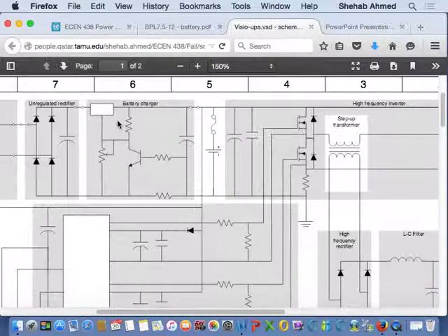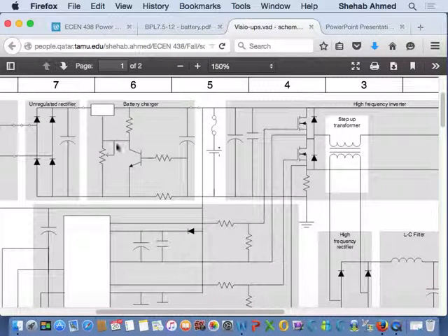So everybody gets that? So we know that this is bad design. This is very bad design, but we added it in there intentionally, right? To make our life easy, as well as to say that we're teaching you something, okay? So no, it's not a good design. And this is somewhere where I don't care about power electronic noise, or switching noise, or changes or ripple voltage. I don't care too much about it here, right? It's easier because the board then becomes a nightmare to build otherwise, as well as it's educational because then you understand, okay, linear regulators.